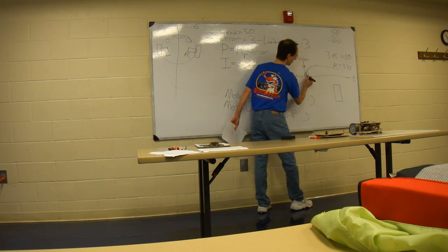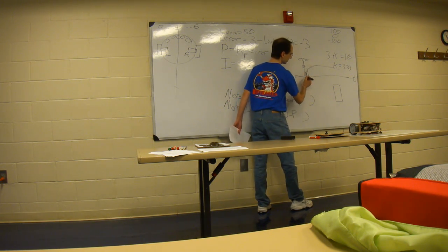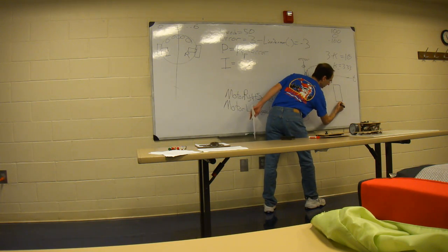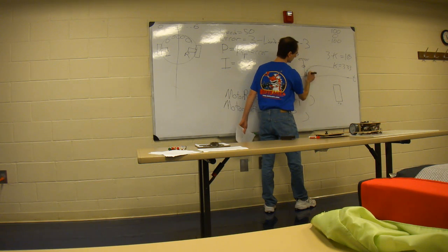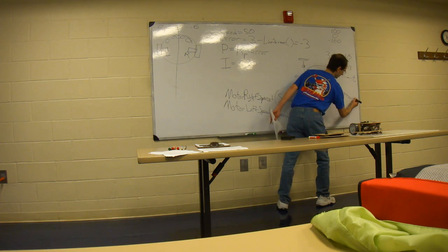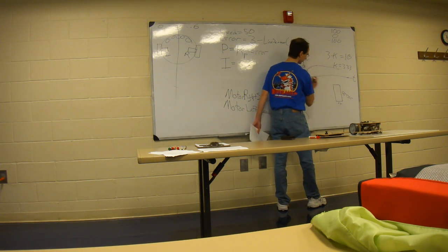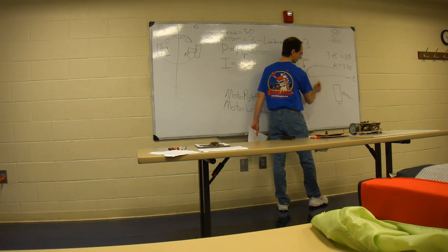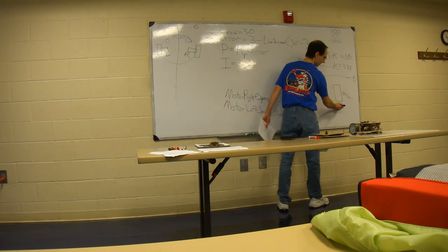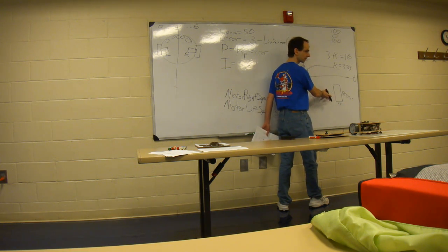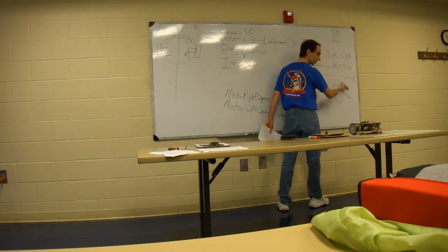This is the time base, so this would be our loop time, and this would be the error. To get the area of this little piece under the curve, it's just the error times the loop time, because the area of a rectangle is base times height.